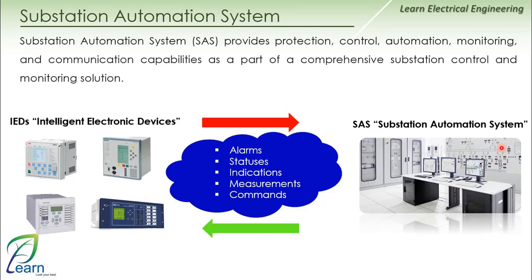For example, the gas alarm, whether it was low stage or high stage, the DC circuit supervision, or something like an overload on the motor of the circuit breaker, for instance, or the alarm between the disconnector or the earthing switches and so on. I also had something called the power meter, which would read the values of voltages, currents, frequency, power factor, active and reactive power, apparent power, and so on. This was, of course, through the current and voltage transformers present in the GIS.